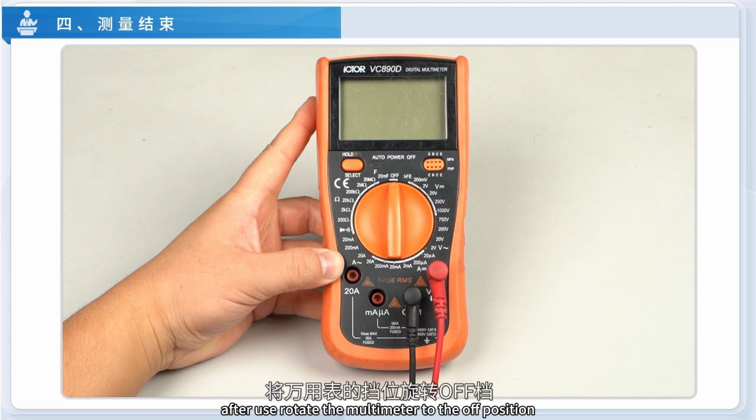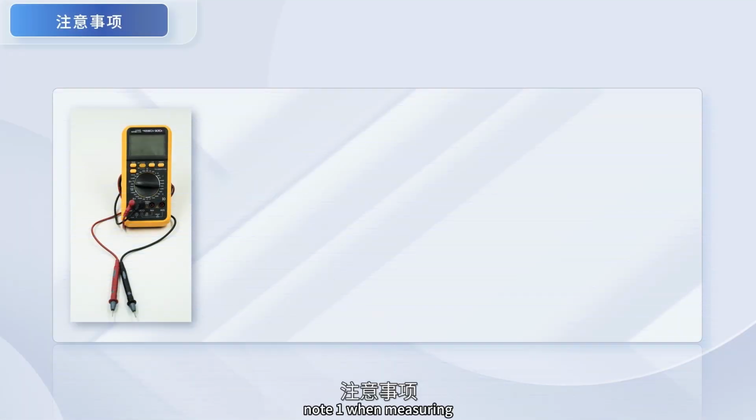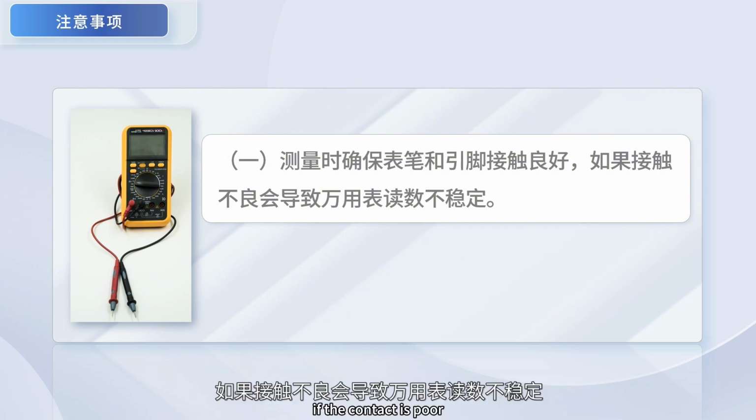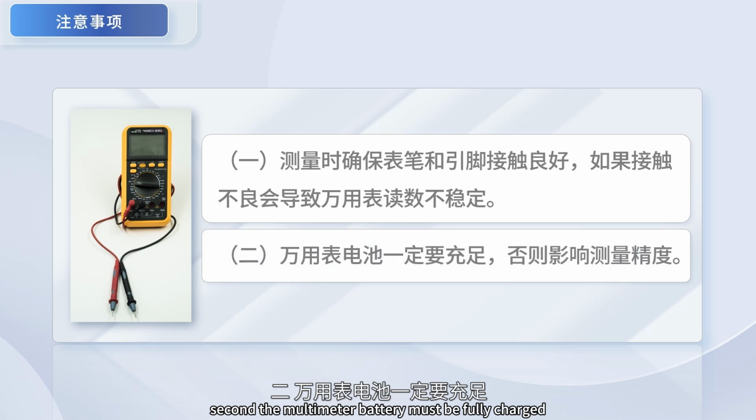After use, rotate the multimeter to the off position to prevent battery power from being consumed due to long-term disuse. Note 1: when measuring, make sure the probes and pins are in good contact. If the contact is poor, it will cause unstable readings of the multimeter. Second, the multimeter battery must be fully charged, otherwise it will affect the measurement accuracy.